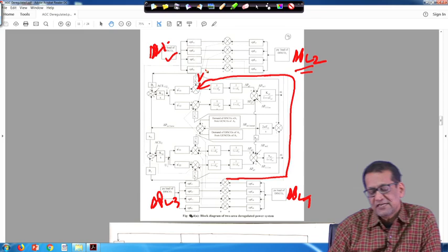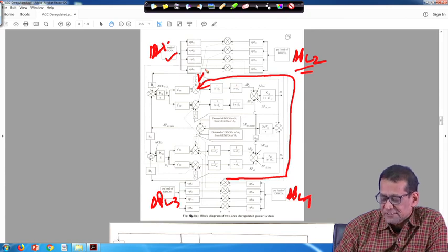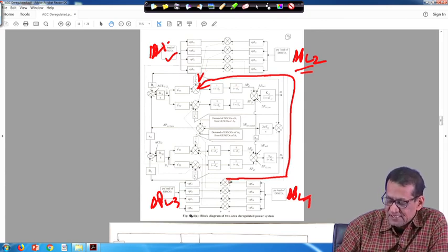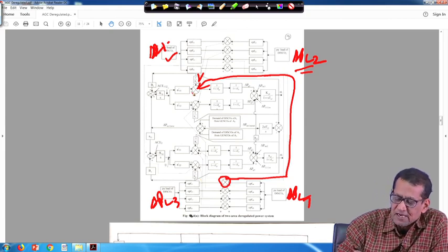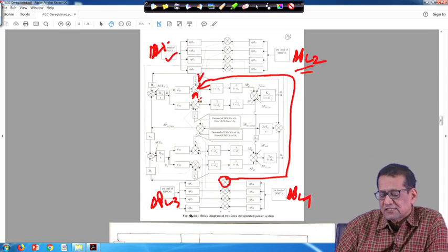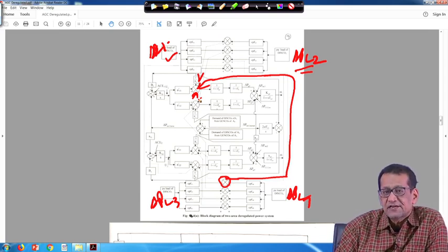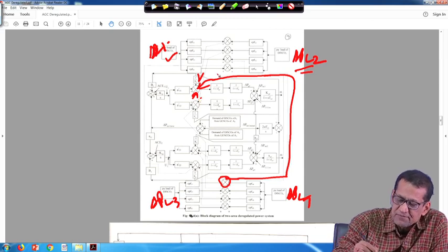So that is your delta P1, the contracted power demand, CPF11 delta PL1 plus CPF12 delta PL2 plus CPF13 delta PL3 plus CPF14 delta PL4. All are coming together, which is mathematically what the GENCO has in the contract.